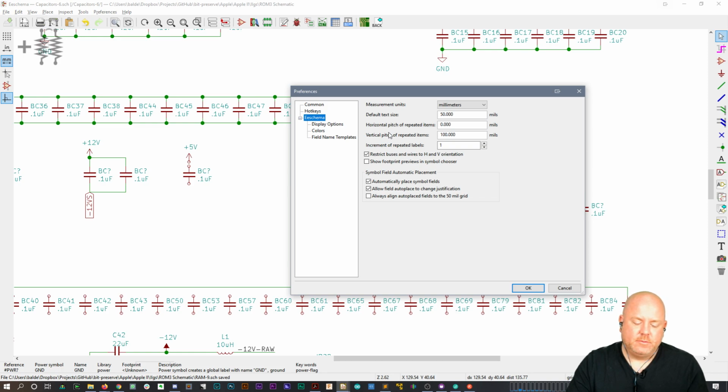How to make a capacitor power bank without a supercapacitor? Actually, if you look at solid state disk drives, they don't use supercapacitors. They use high energy tantalum capacitors or tantalum polymers, which are like 1500 to 2000 microfarads per cap. But in that case, they're only charging to 5 or 6 volts. The challenge with using a supercapacitor for a power bank is that they have a really low working voltage, like 1 to 3 volts, so you have to series them.